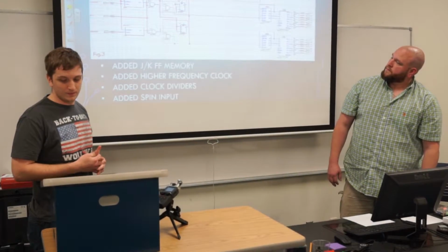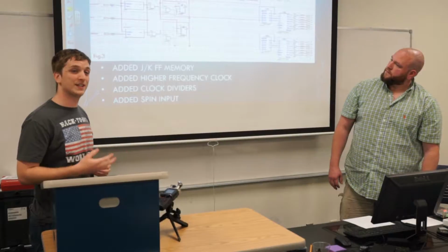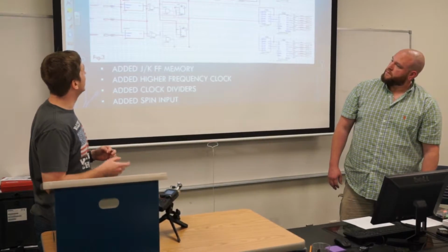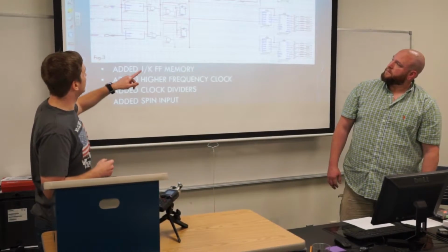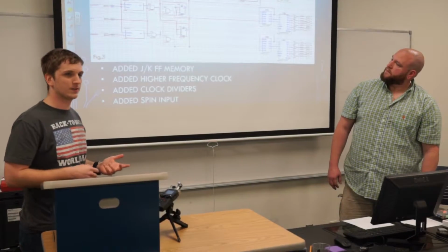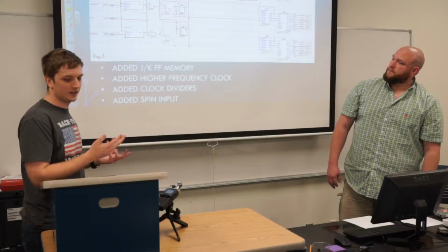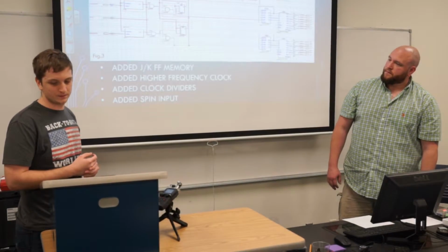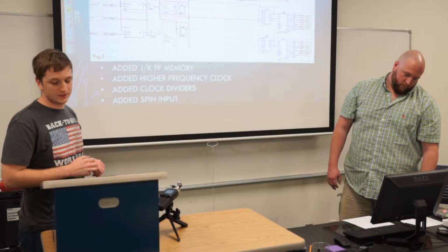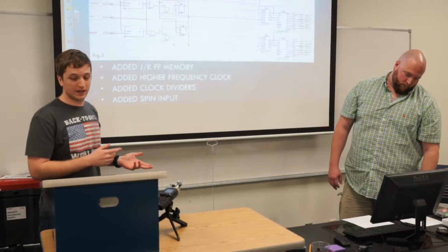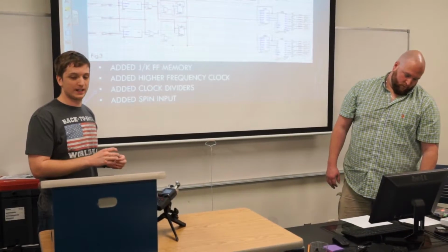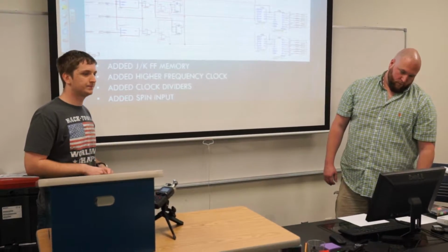The flip-flop functioned as a toggle, since both the J and the K signals were tied high. So if you push the button, it would toggle instead of going higher or lower. The end product was a push button that would stop the clock from counting as soon as the button was pressed, and it would display the last number the counter had output.